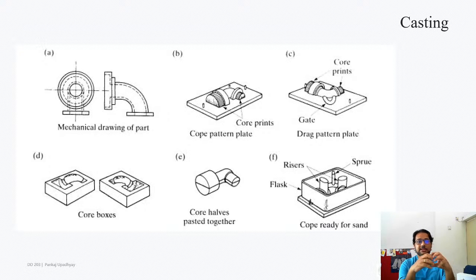Okay, a core is another piece of material, not metal, which is made out of a slightly more bound piece of sand in terms of sand casting. And once a pattern is created, let's say the slingshot had a hole in the center. Once the pattern is created, you remove the cope and the drag, and in the cavity that is created, you put this core.